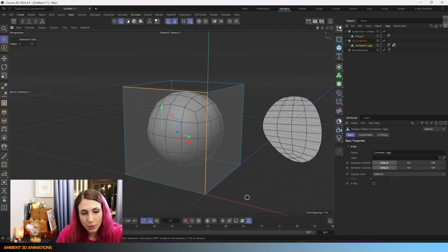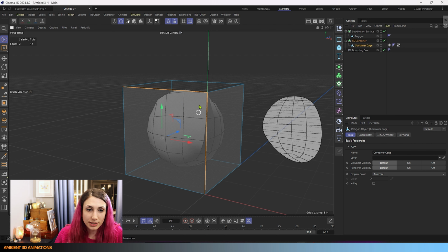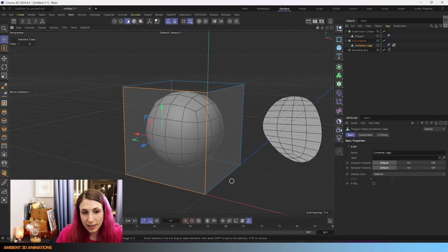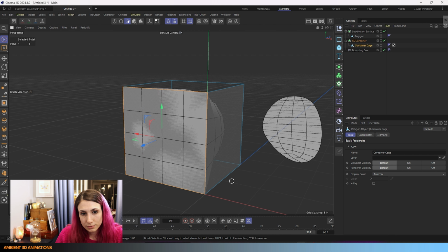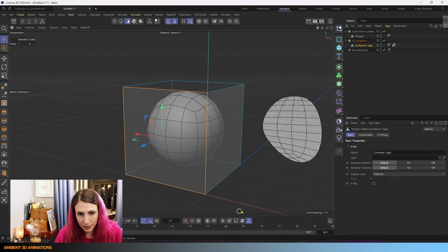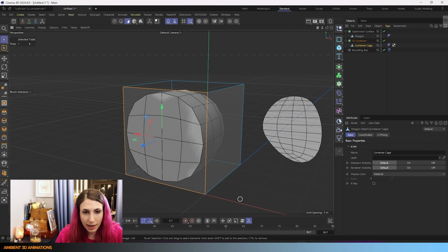And just holding this button and dragging, you'll see that's becoming rounded. If you hold down the period button with control, it won't be as rounded. It'll be a little bit of a sharper point here. So you can see how that affects your mesh, and you can see that even more if you do this with polygons. So the same hotkey as before, if you just hold the period button and click and drag, you'll see how this is affecting it. You can try control the period button, click and drag, and now it's rounded.